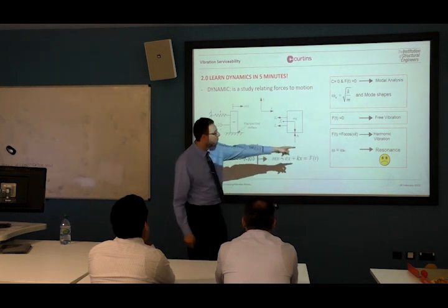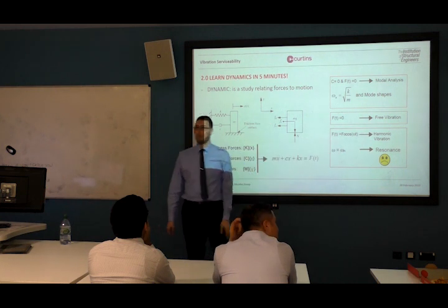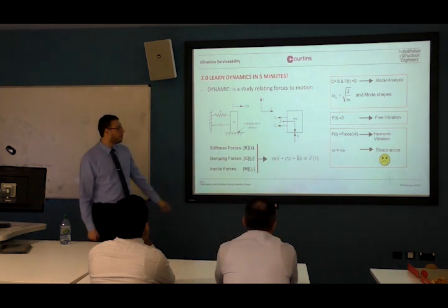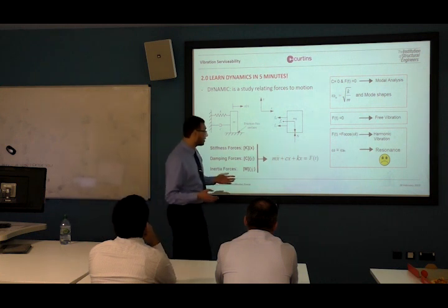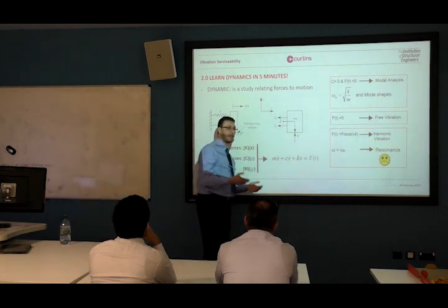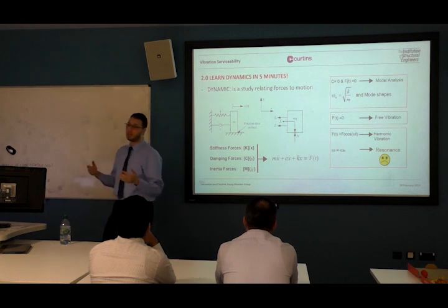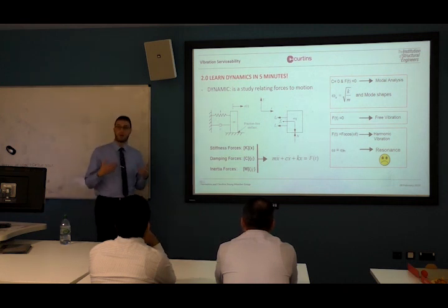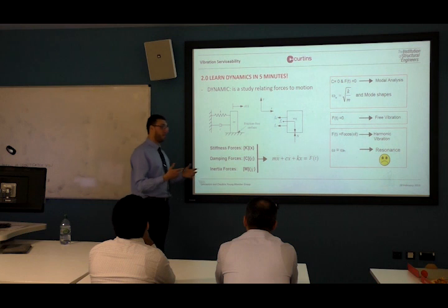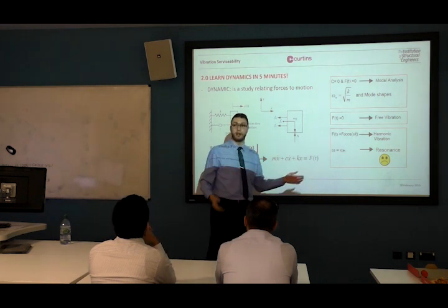And that's why you have my sad face here, because this is what we call resonance. Resonance is a very nasty phenomenon, because it kills your mass, your inertial forces, and your stiffness forces, and the only thing resisting the excitation will be the damping.